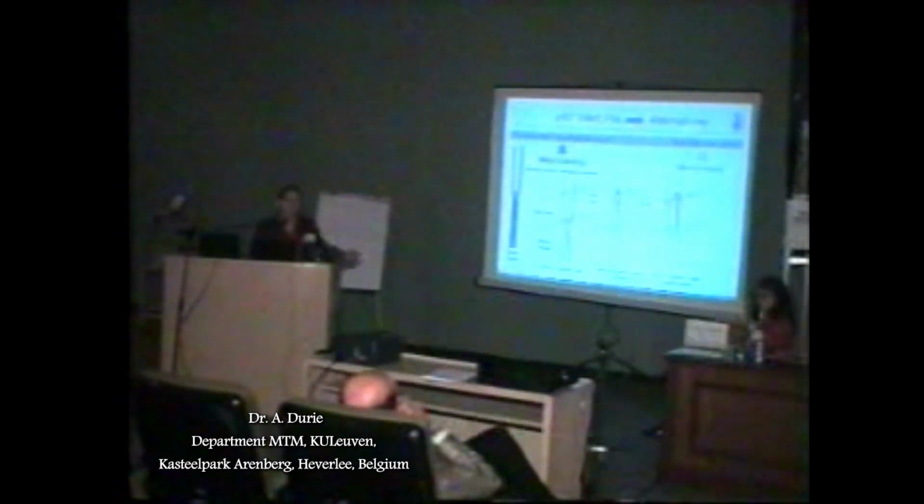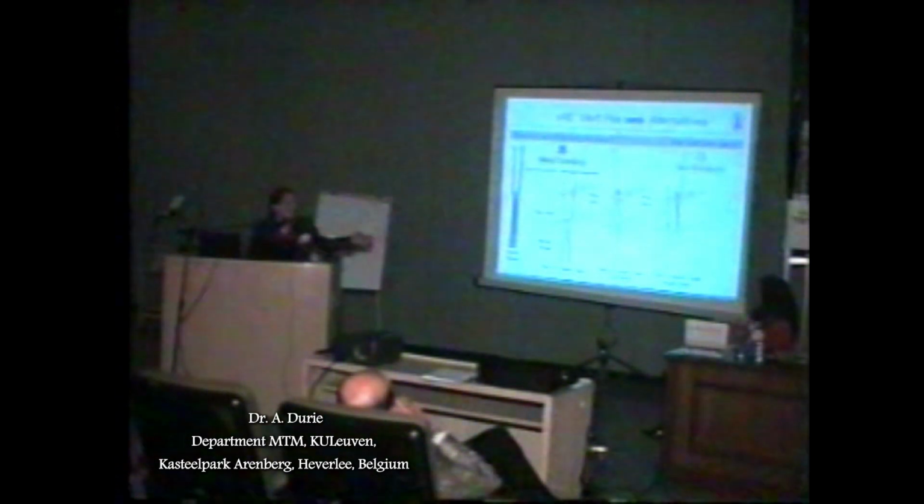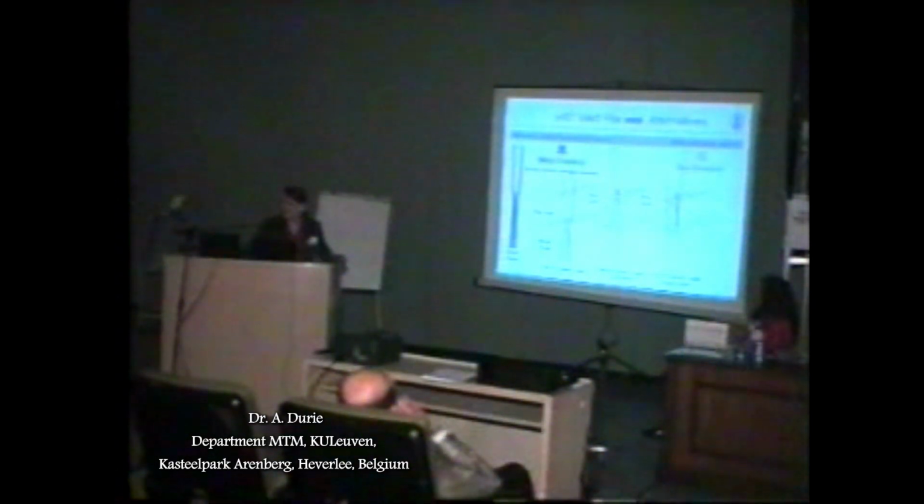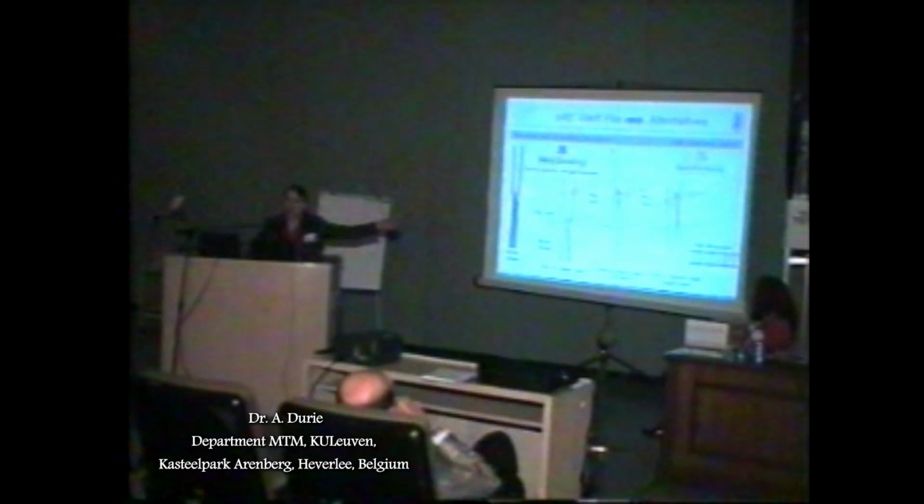You can see the metal dupe positioned in the bottom layer on the left-hand side. If you lift the left-hand side of the dupe, you get a left shift of the pile in the upper layer. If you lift the right-hand side of the dupe, then you get a right shift of the pile. And the resulting structure in the weft direction would look something like the pile structure that's down here.